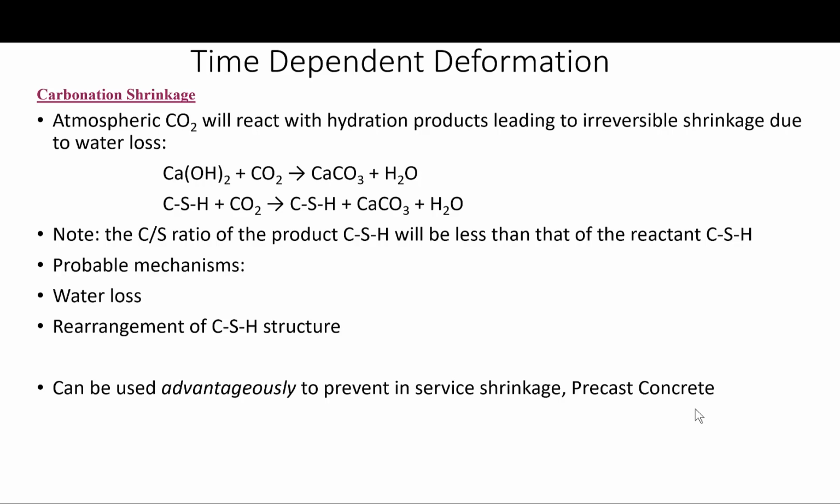At high humidities, carbonation is low basically because the pores are mostly filled with water and the CO2 cannot penetrate into the paste very well. At very low humidities, an absence of the water films is believed to lower the rate of the carbonation. That's what I have gathered, okay?